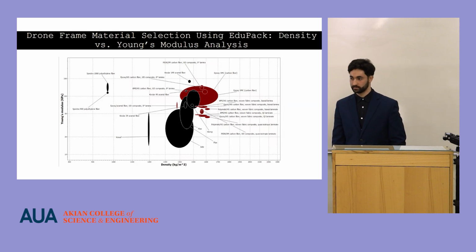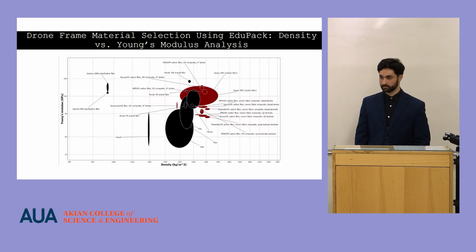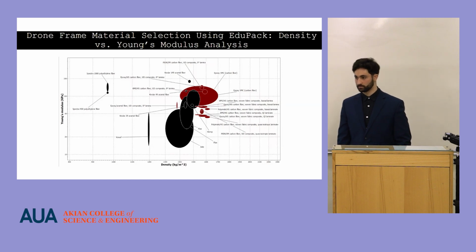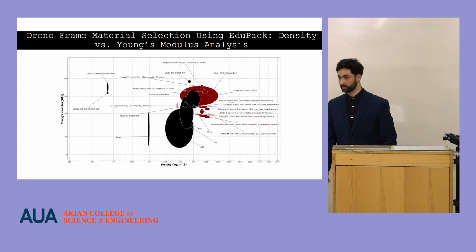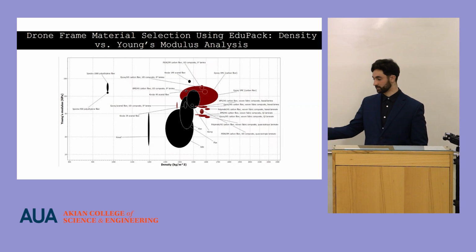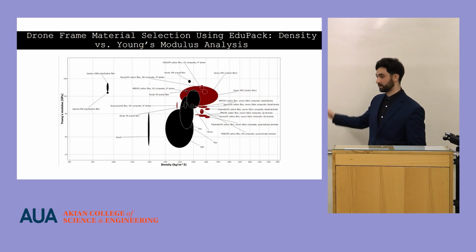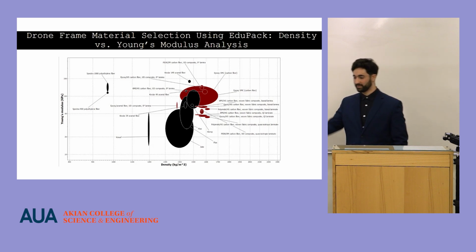One more small comment. Working in a closed environment, it would be really important to have rangefinders on all of the sides of the drone for safety reasons. Something like ultrasound, or it can be a laser or anything. There is ultrasonic, so it can detect altitude and its surroundings. I mean rangefinders across the perimeter, so it detects the wall with sound, to avoid collisions. I have that only facing down, but I can definitely add more.